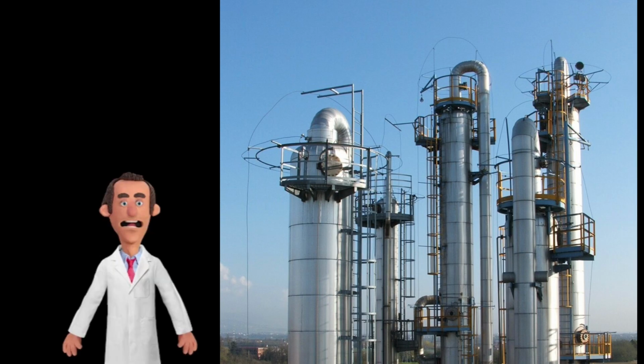So in this project, I combined the McCabe-Thiele method, UniSim process simulation, and MATLAB to optimize the operation of a binary distillation column. I studied the effect of feed tray location, reflux ratio, and number of stages. An optimum operating condition of 23 stages, feed tray 13, and reflux ratio 1.9 was identified. This reduced the total column duty from 4,323.6 kilowatt to 2,287.2 kilowatt, resulting in approximately 47% energy savings while maintaining the required product purity.